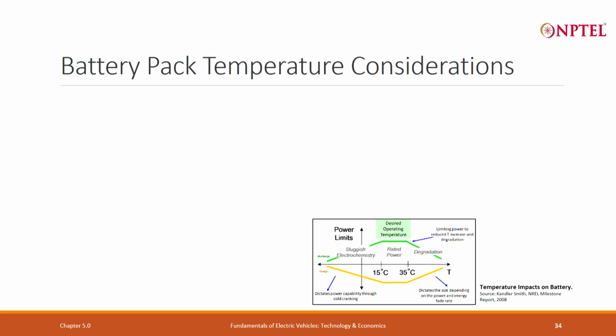So, for the current cells, for current NMC cells or other varieties of cells, the temperature range is something between 15 degree to 35 degrees C. So, if the temperature is in between that, you can get based out of its life, calendar life as well as cycle life, and it will perform well. And then we also mitigate different type of accident which can happen. One of them is thermal runaway, other things like melting of materials or electrodes here and there.